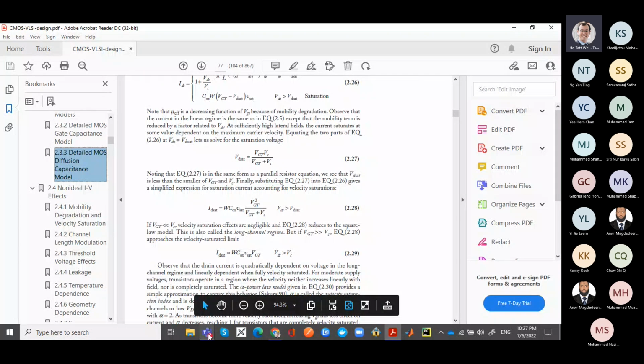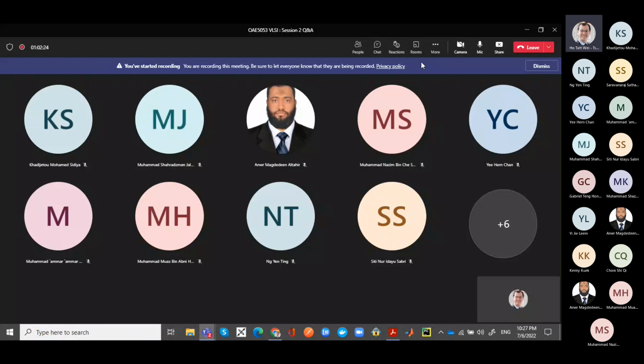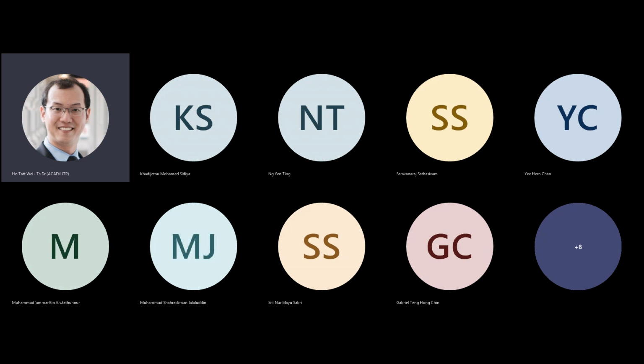But where we're going with this, as I mentioned, is our desire to model the switch transistor networks, the logic gates, as resistive and capacitive elements so that we can estimate the speed of switching these devices using the RC time constant. So from your basic electrical circuit analysis, you can actually infer that.